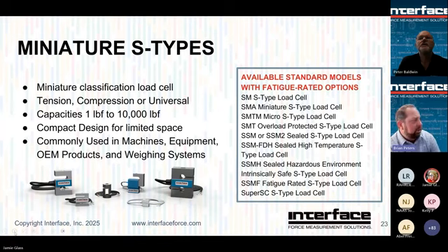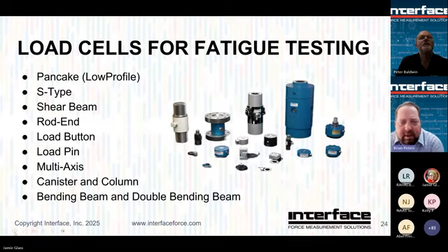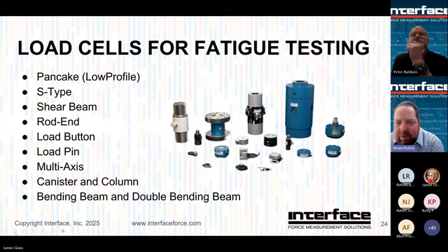The reality, if you go to the next page here, Jamie, the reality is a lot of sensors can be used in fatigue. Don't necessarily be afraid to use something in a fatigue test, but it's really important that you understand the loads it's going to see, and you discuss with one of our application engineers to make sure it's operating at a lower limit, and you've also taken into account other aspects to make sure that it's going to be adequate for your use.